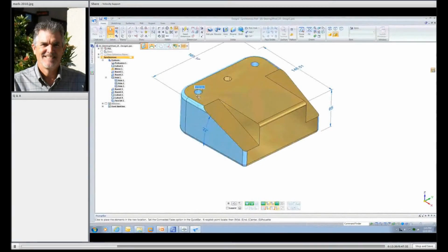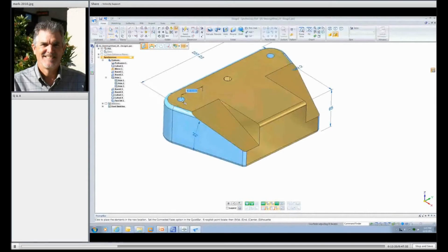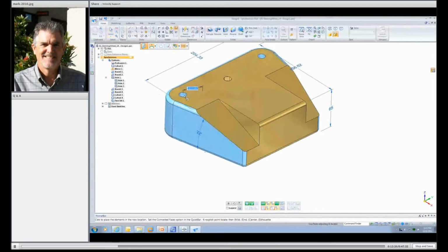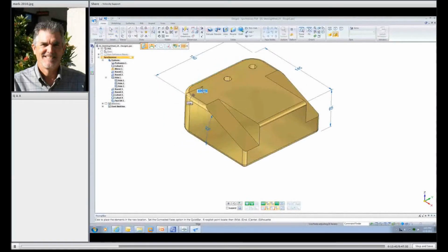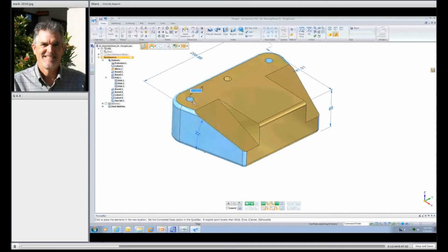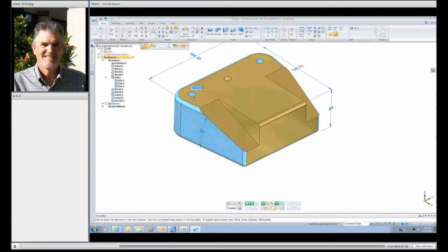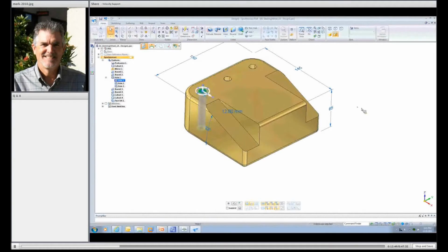Now you'll also notice one other thing with these holes is there's actually three of them. And we obviously have concentricity turned on and tangency turned on, but what about that center hole? One of the other Live Rules that's on by default is what we refer to as maintain coplanar axis. So when you have holes aligned, in this case in the Y plane, if you turn that particular option on, now it's going to maintain those holes in line as you would expect it to do.